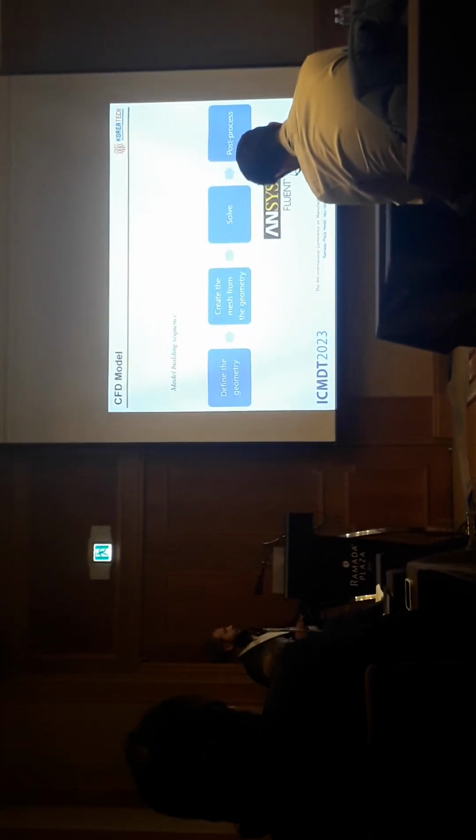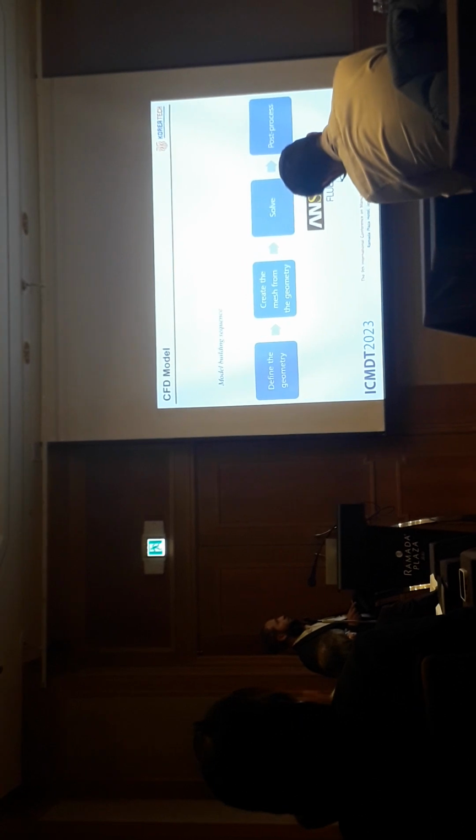So the model building sequence started with defining the geometry, and then creating the mesh, which is a quite challenging task to do, and then solving. We used ANSYS Fluent software to do the solving process, and then did post-processing to get some results. So for the case study we handled in this study, we have 4 basic cases.